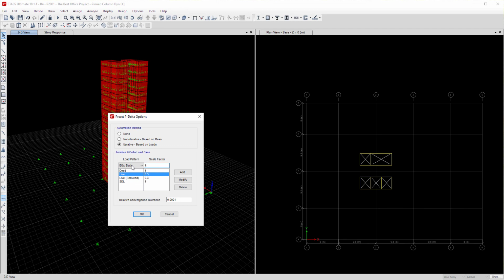So we've seen that in the X direction, it was almost the same. This is a limited ductile case, so we need to factor it up by 2. And in the Y direction, it was about 65%. So we can say it's a 65%, but we'll factor it up by 2. And we'll add that, so it comes up to 1.3. Now we've added equivalent static forces to represent the dynamic earthquake results that we were getting for our P delta checks.